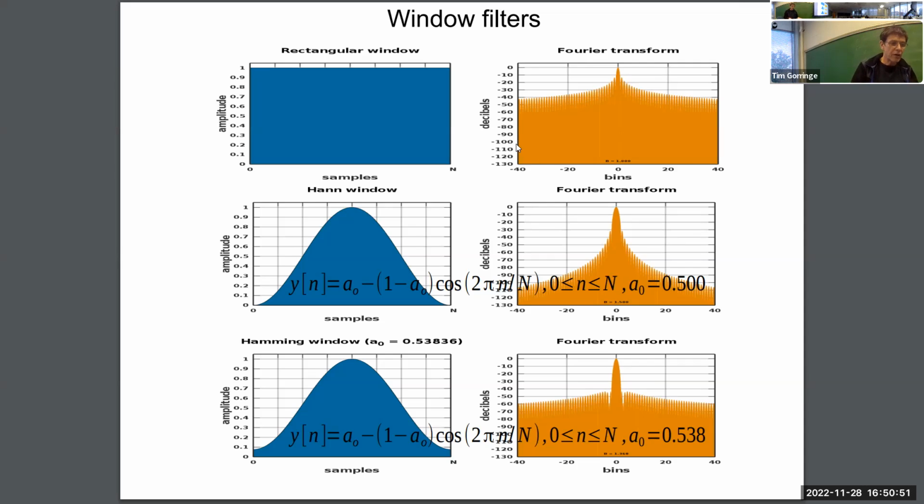As we argued, if you go to higher and higher frequencies, you get more and more cancellation of the oscillations of the signal in your window, whatever your window. And so you get less and less of that signal through your filter. That's what you're seeing. If you go over to the far right, you've got strong attenuation of higher frequencies, and the same over here on the left-hand side. It's just showing the strong attenuation of high frequencies.